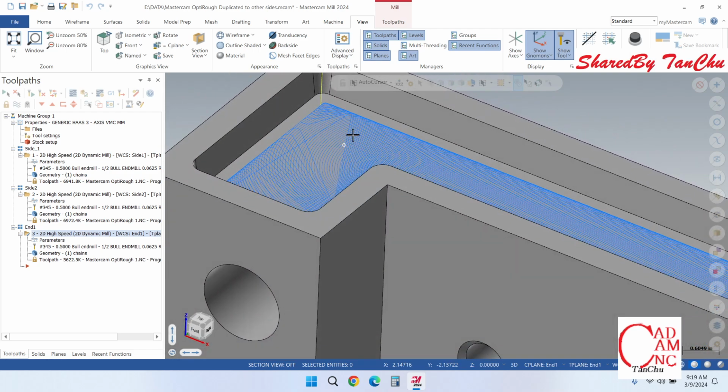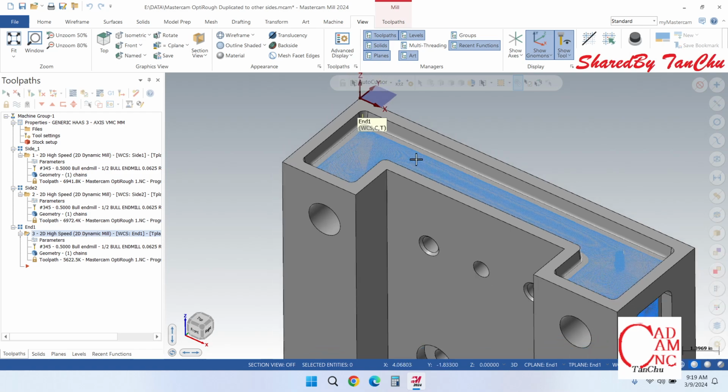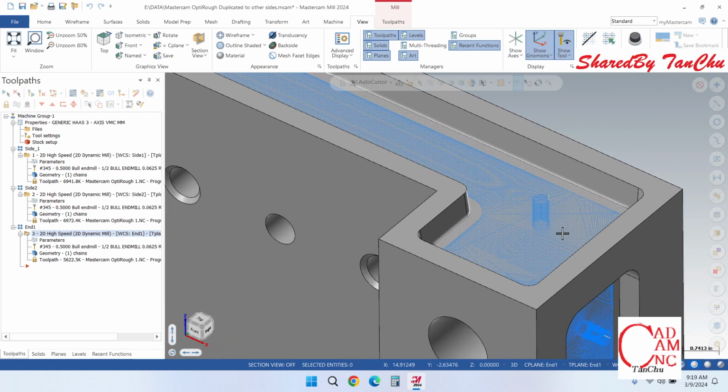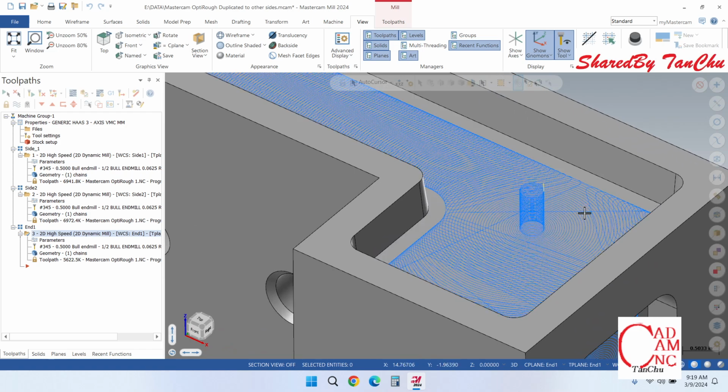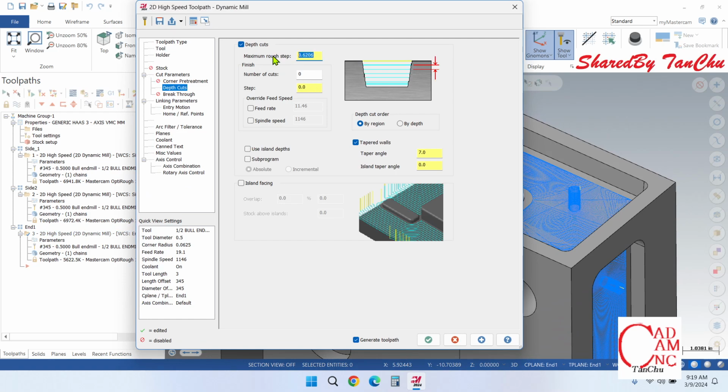and when we run the taper, we cannot run only one pass, like helical down and run only one pass. We need to run many passes to make the angle. So if we need it smooth, we run about a depth of about 25, and if we run the 25, we run the step over bigger.